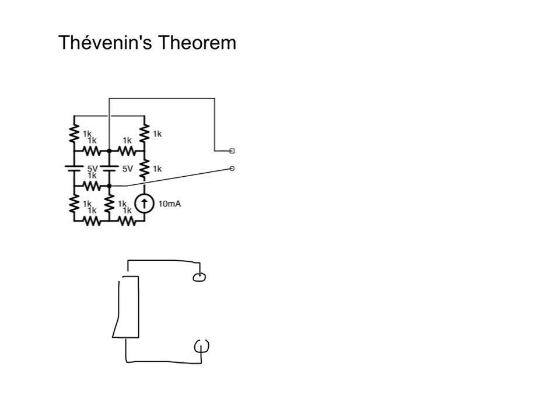And so the first thing we might ask is, what is the voltage between the two nodes, measured with a voltmeter? And that's essentially what is the voltage when those two nodes are connected by an open circuit in this abstraction. So we can call that voltage V open. Open circuit here doesn't mean that it's open here. Obviously, in this particular example there are various connections between the nodes, but we haven't added anything ourselves between the two.